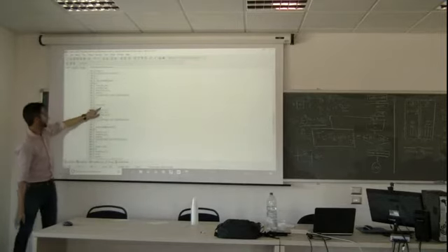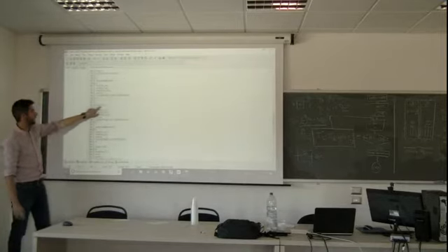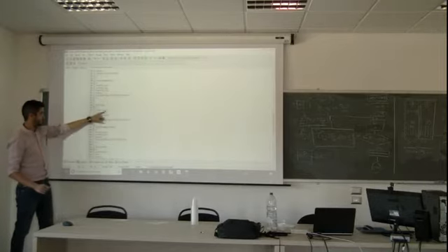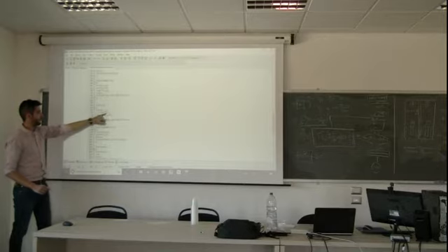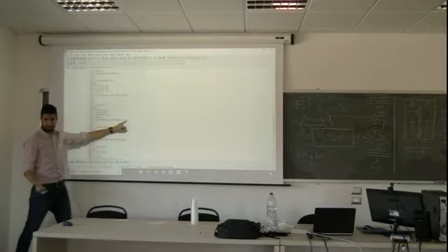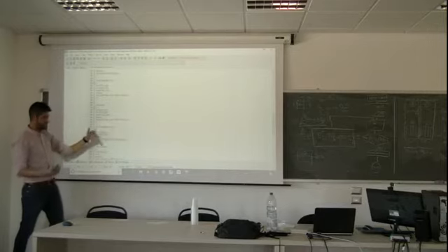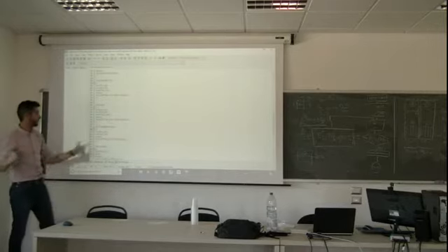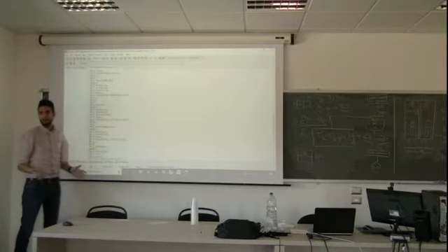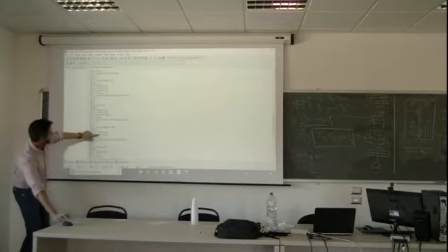Here we go. For the node in the middle, you will have B, this term, C, this term, with different delta x. You will have generation of heat just in the half of the first delta x, but the equation has the same shape: B multiplied by the previous temperature, C multiplied by the following, plus an independent term, divided by the denominator.